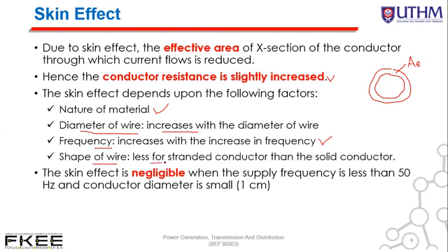Skin effect is less for a stranded conductor than a solid conductor. If you have a combination of conductors stranded in a bundle form like this, compared to a solid single-piece conductor, the skin effect is less in the stranded type.